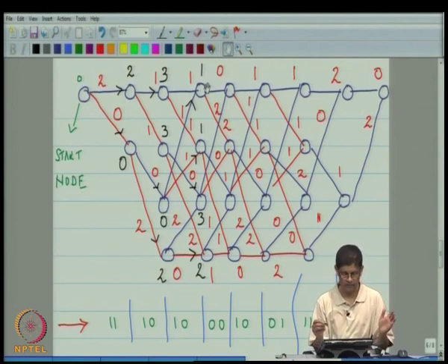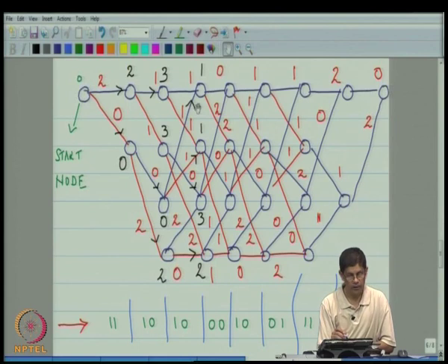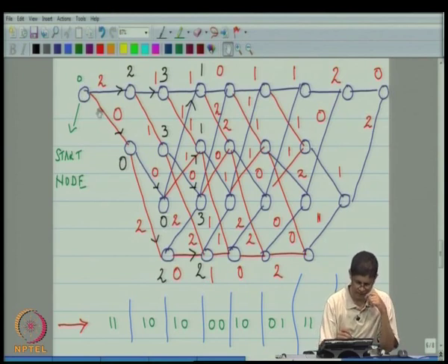So, the relative comparison remains, and so you have a loser here that can never be the closest code word. So, what remains are called the survivors. So, at each node you have a survivor, and the survivor metrics are 1, 1, 3 and 2, and you also attach them to the node, but really they are the metrics of these survivors.